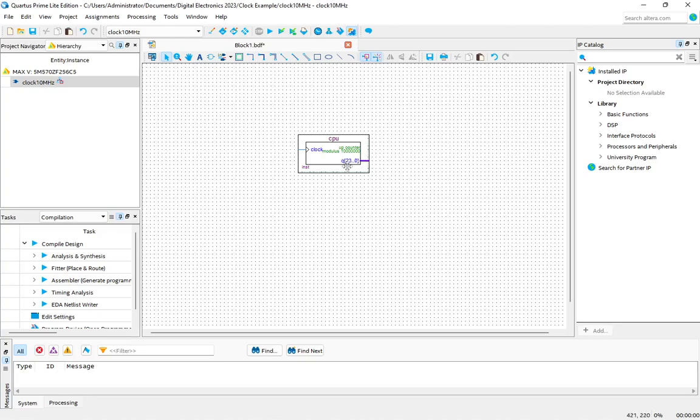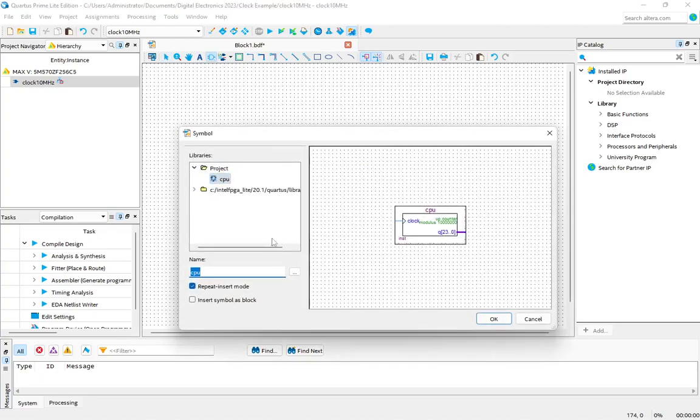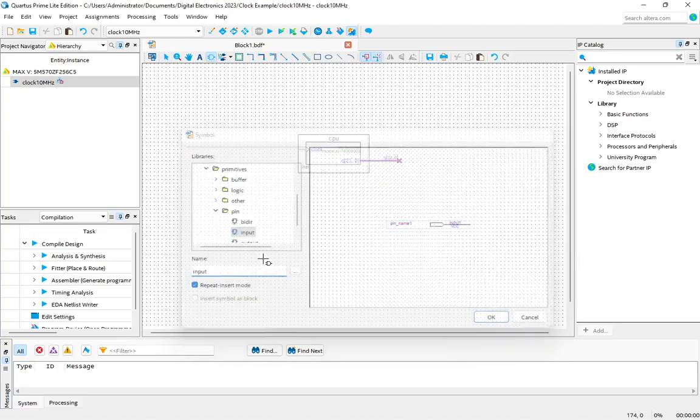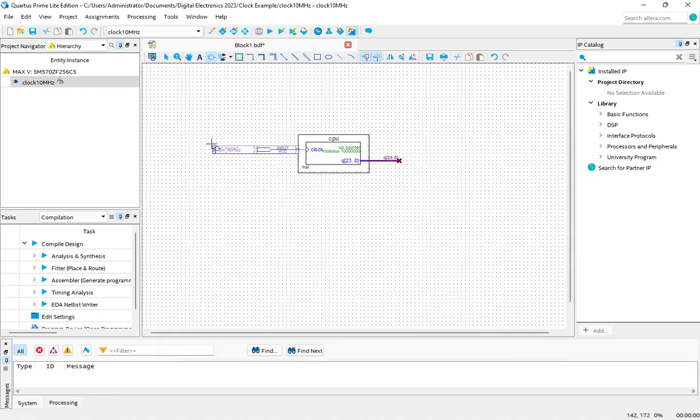See, this line here represents 24 bits, 23 to 0. So just drag it out like this, and then rename it. You can click it and press the space bar and name it as it is on the label. It's 23, 2 dots and 0. So that's 23 to 0, and this one is your input. That is your CPU.